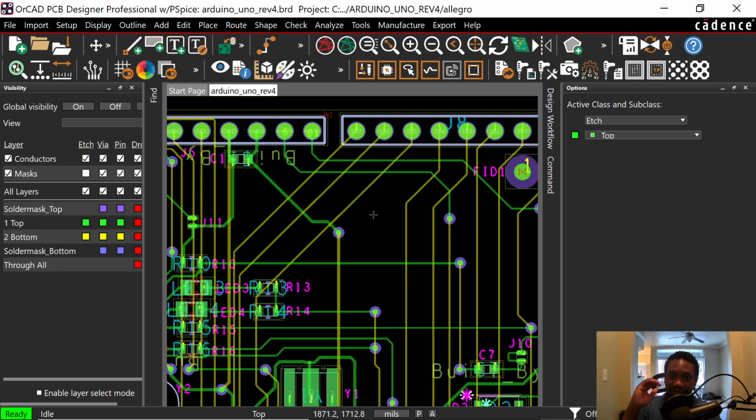We can design it in such a way that we maintain certain clearances and we maintain certain spaces and line widths, and what width does the trace have to be, and all of these questions. There are rules that we need to design by in order to make sure we don't do extra work or redo work.